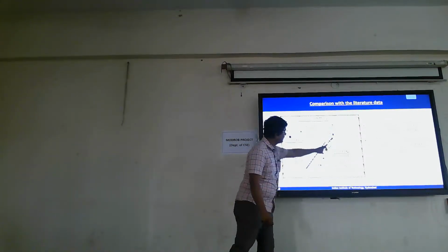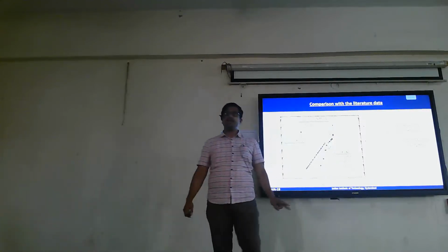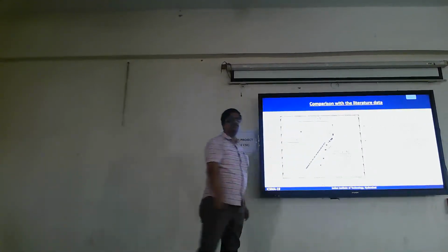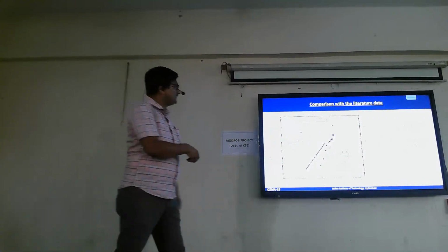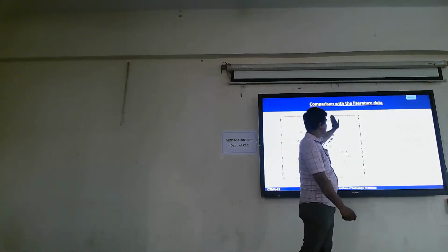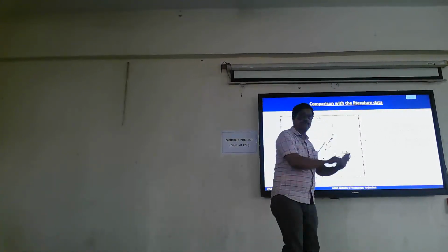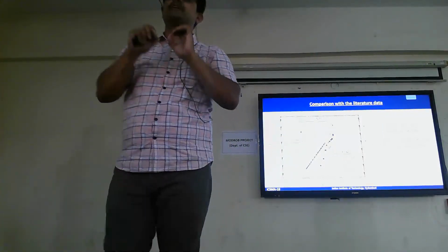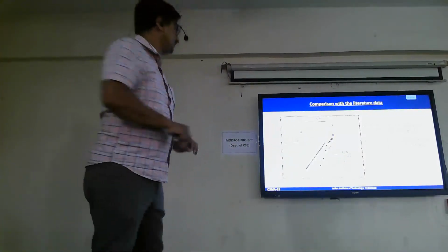And if you see the slope, it is n equal to 3. This is the power law breakdown region, but mostly n is equal to 3. So my point is there is a transition from the n equal to 3 region to the power law breakdown region. This is an exponential relationship, and there is no significant primary creep. No significant primary creep is one of the signatures for this kind of creep. I'm not going to go deeper into that.